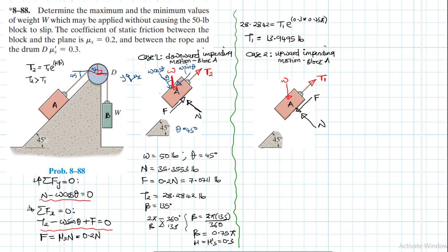And later on, we are going to have components in that manner. This angle being theta, and we know that our theta is equal to 45 degrees. So this becomes W cos theta. Then we'll have another component in this direction, in the horizontal inclined direction. This one is W sine theta. I think we are done.